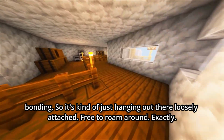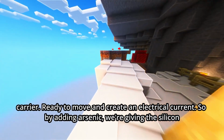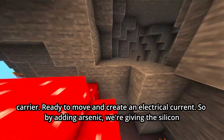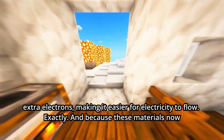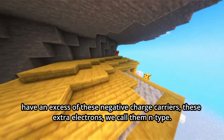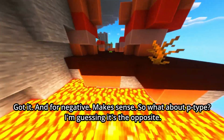Free to roam around. Exactly. It doesn't take much energy at all for that extra electron to break free and become a charge carrier, ready to move and create an electrical current. So by adding arsenic, we're giving the silicon extra electrons, making it easier for electricity to flow. Exactly. And because these materials now have an excess of these negative charge carriers, these extra electrons, we call them N-type. Got it. N for negative. Makes sense. So what about P-type? I'm guessing it's the opposite.